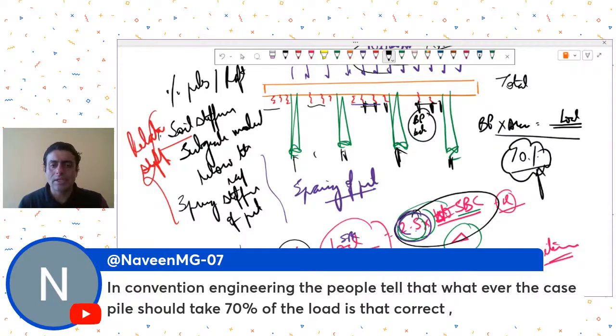If that is your desire, then accordingly you need to ensure that the pile spacing is provided in a specific manner. You also need to check the strata and, for that strata, the load settlement curve of the pile. From that, you calculate the pile stiffness. You also need to check the subgrade modulus that will be offered by the soil at the level where you are going to provide the raft. Put that value also, then see what percentage of load distribution you are getting. Understood?